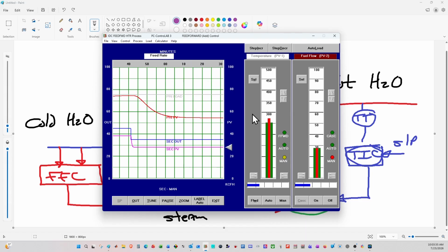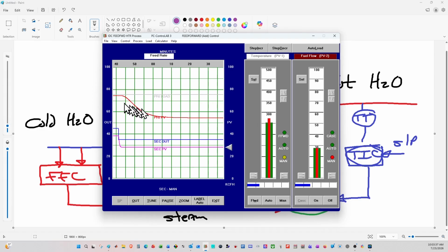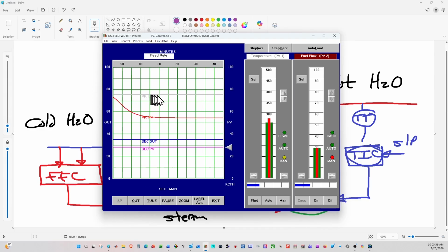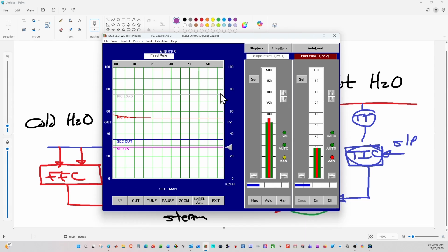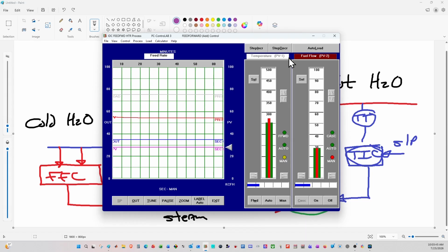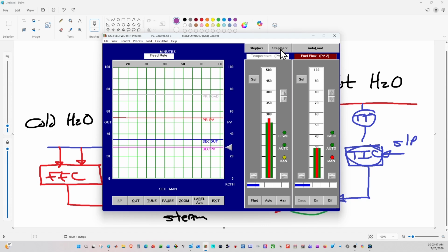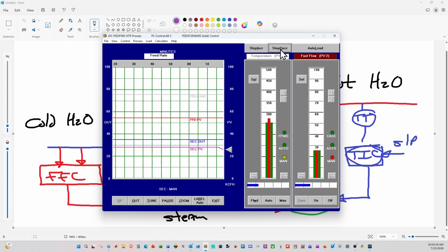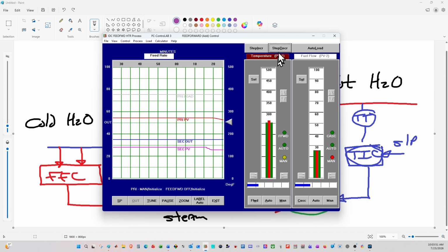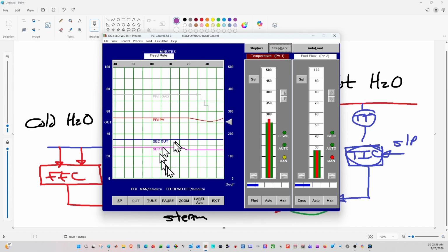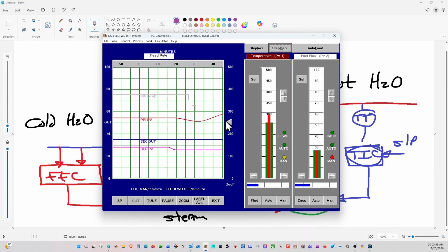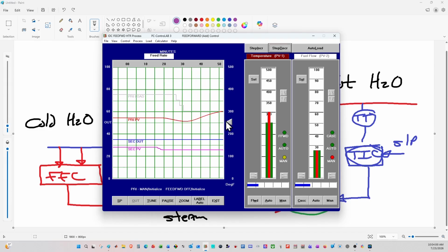There's also going to be the feed forward part of the loop. I want you to look at that gray pen where I'm drawing the line right now, and imagine that is the load that is going into my boiler. Now, if I was to decrease the load, in other words, if I was to put less water into that process, then what you are going to find is that with less water and the same amount of heat, we are going to have the temperature that will go up.